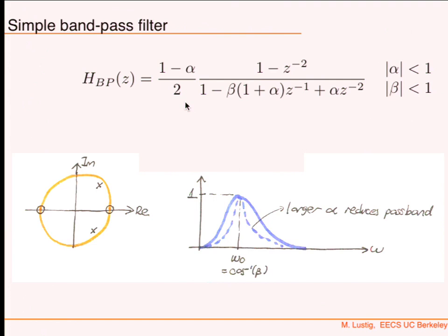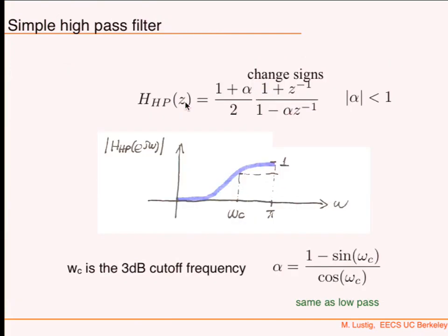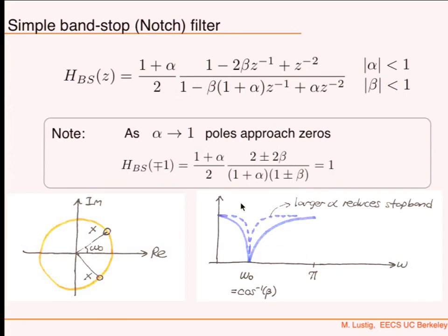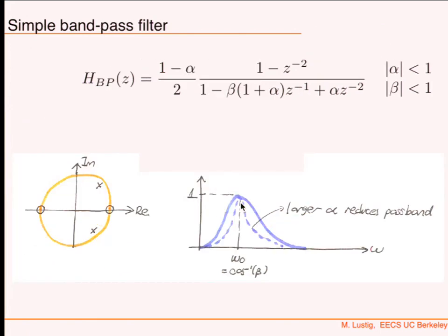Yeah, pretty much. But this is a specific parameterization that allows you to come up with some very simple filter characterization. So you want a certain width, or in particular for the case of a low-pass filter, if you want to design a certain cutoff frequency, you immediately know what is the value that you need to put for that system in order to achieve that. Okay.